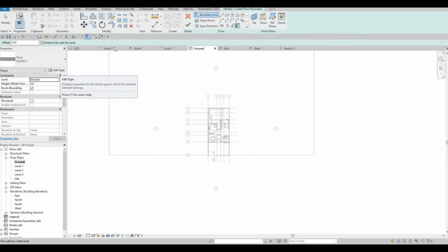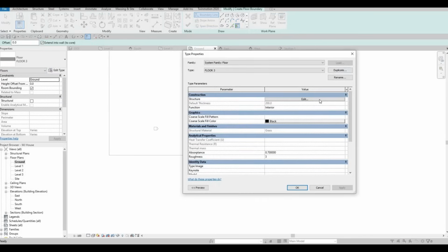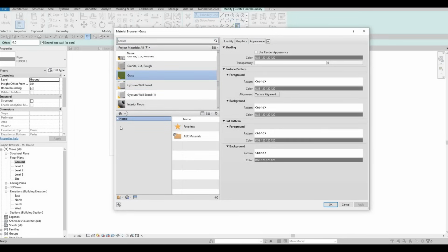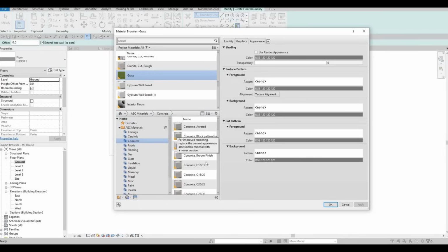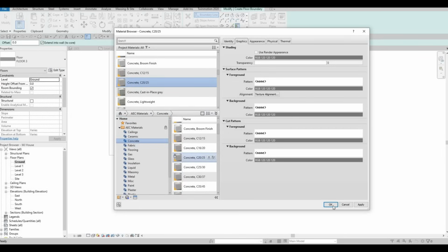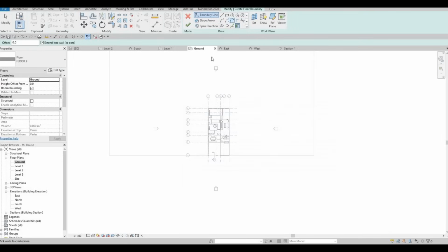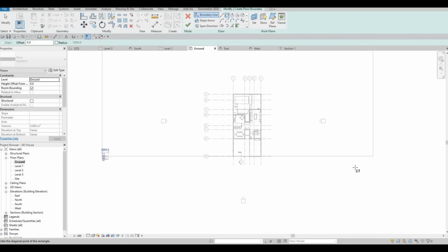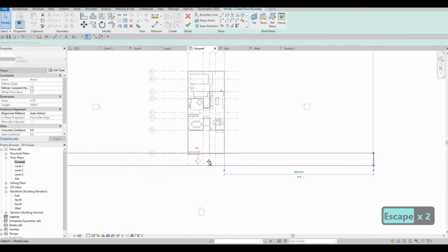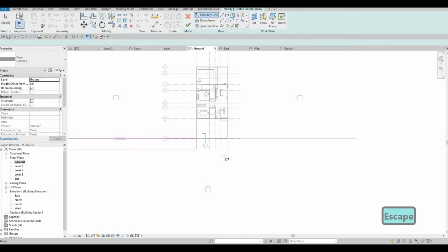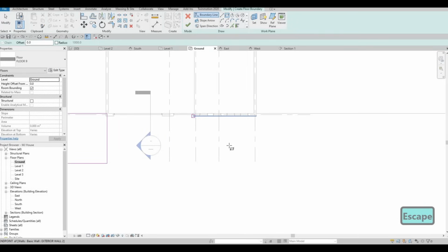So what we're gonna do is create another floor, and then we could just add a sidewalk. So edit, duplicate, this will be floor number 9, and then let's change this to concrete. Let's choose a concrete material that we haven't used, and then just place it into our site. We could just do this right here, and then because we need some separation, we could just add something that looks like that, and then here as well.